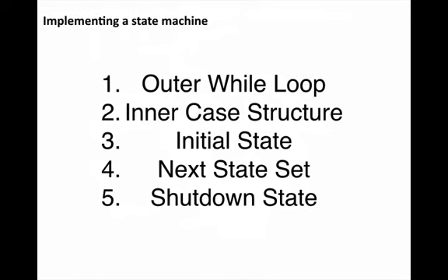And then every state machine needs to have a shutdown state. I am a firm believer in this because things will go wrong, and the shutdown state should be the error condition, or if the user presses like a stop button, the machine should shut off. Or if there's a critical error, you don't want it to just keep running with this critical error or go to some random error state. You want to make sure that things are safely shut off. In the lab, this is especially important. For example, make sure hydraulic pistons are locked, or make sure X-ray sources are turned off, or make sure a shutter to a neutron source is turned off, things that could actually harm you.